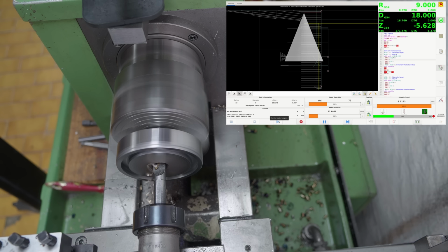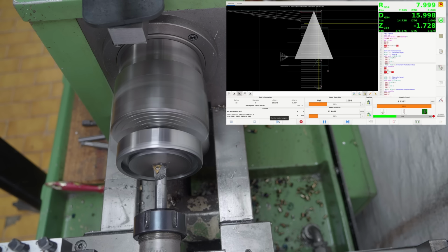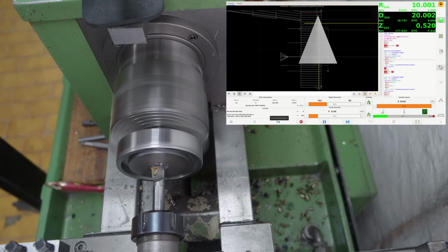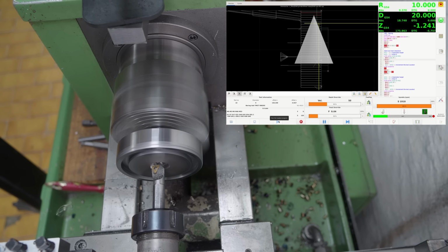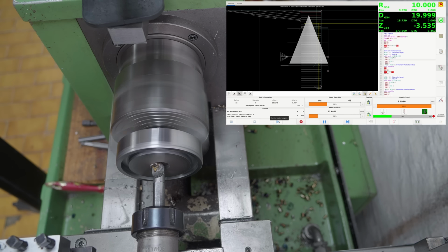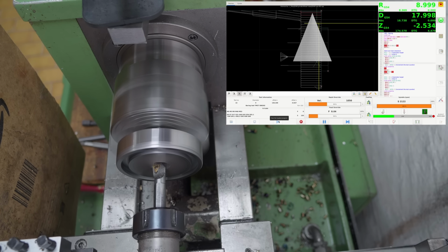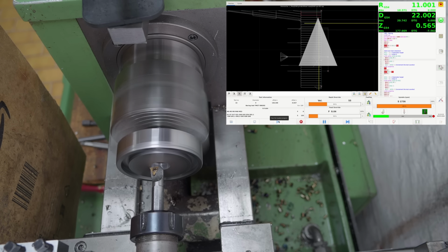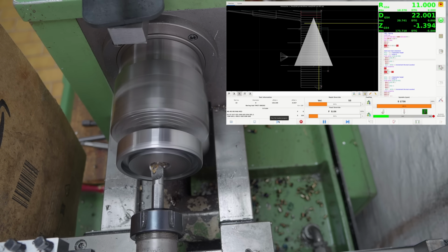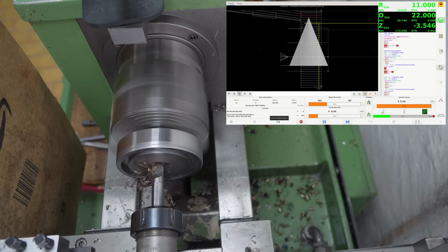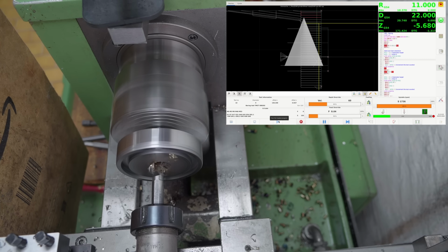As you can hear from the speed changes, it's sort of right with following the constant surface speed velocities needed, but I have to freeze the ratio calculation so much of the time that you get these long pauses where the thing's recalculating, and then halfway through the cut you're accelerating again.